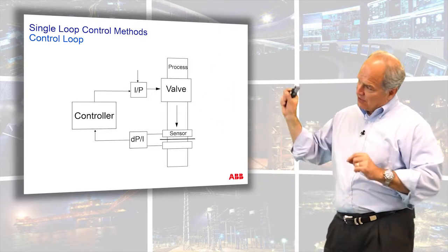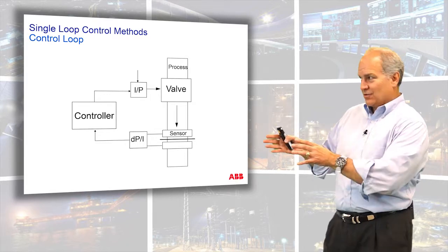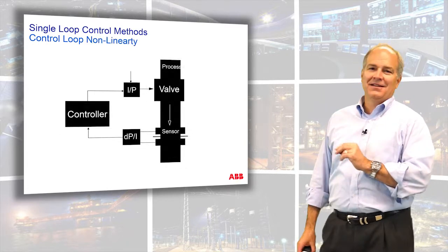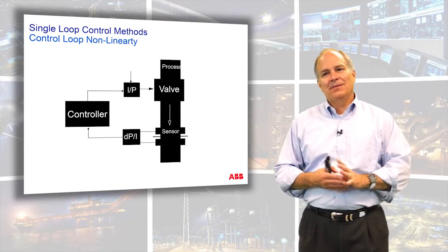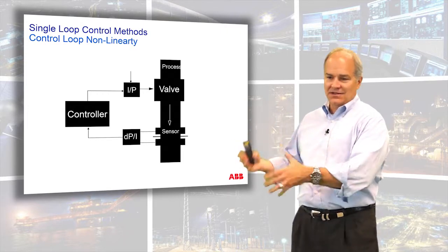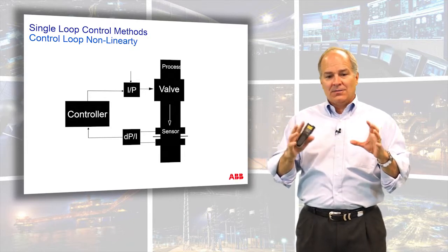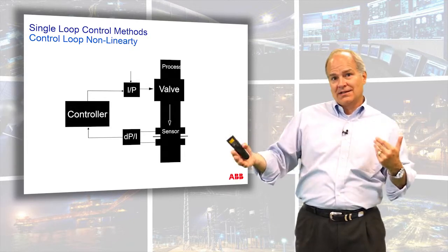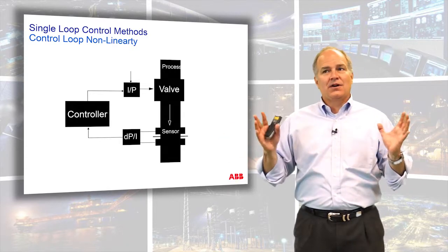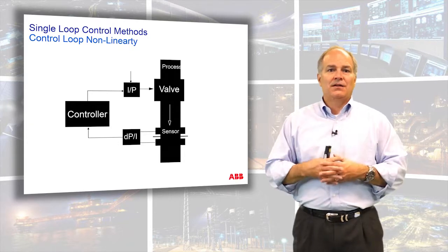So what I want to do is just shade in the areas where nonlinearities can occur. Can they occur in the controller? Boom, everywhere they can show up. Nonlinearities can show up in the controller, the process, the I to P, the valve, the sensor. And so these are those question marks that we talked about. The number of unknowns in your process dynamics is really unlimited. So when we start, we try to minimize the effect of nonlinearities and just look for the big components.